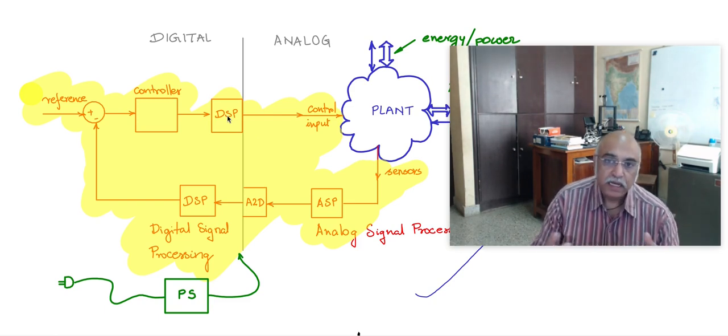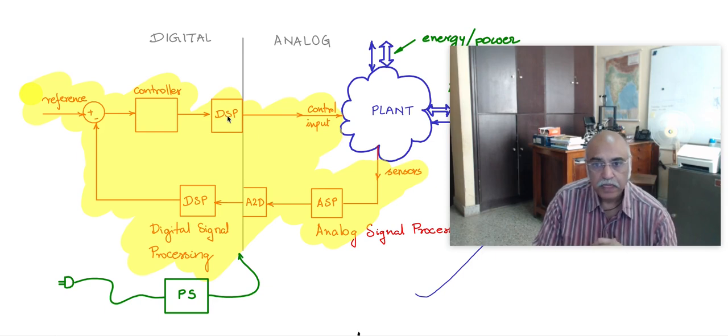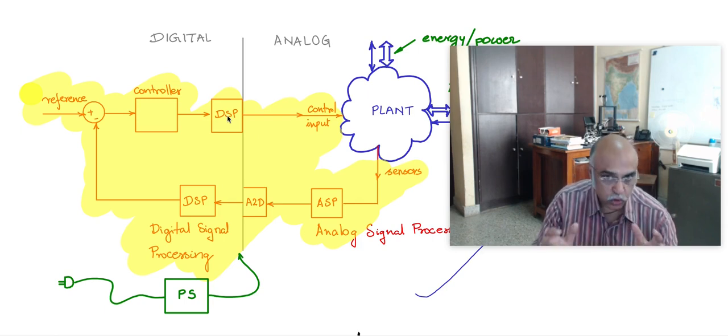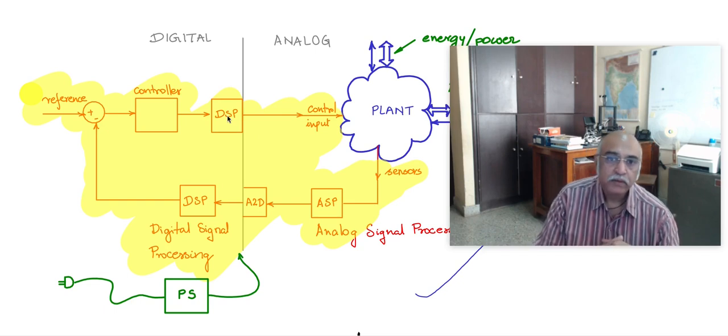taking the signals that are coming in from the analog domain through the A to D, and you should be able to put back into the analog domain through a pulse width modulator or a DAC, such that the entire system is controlled. So you also will be monitoring feedback, gathering the signals, information through the transducer sensors, processing it in the digital domain, passing it through a controller, and the output of the controller will drive an actuator, which is again back to the analog domain.